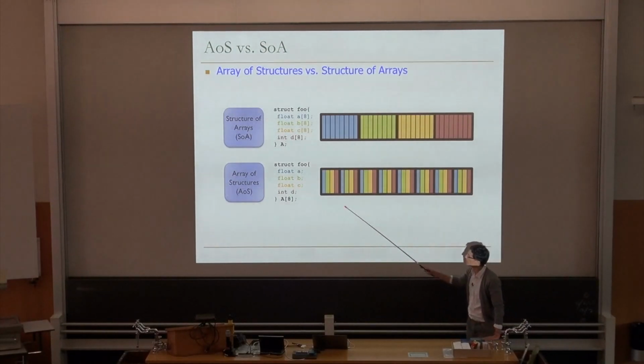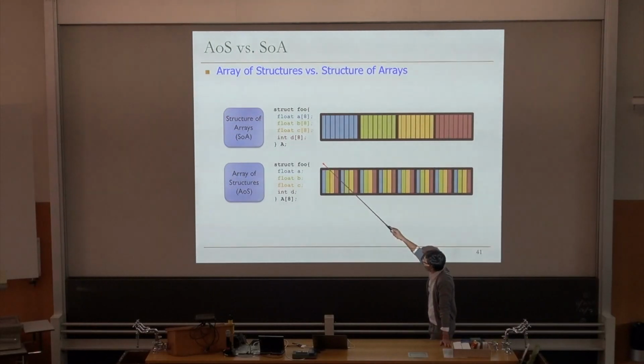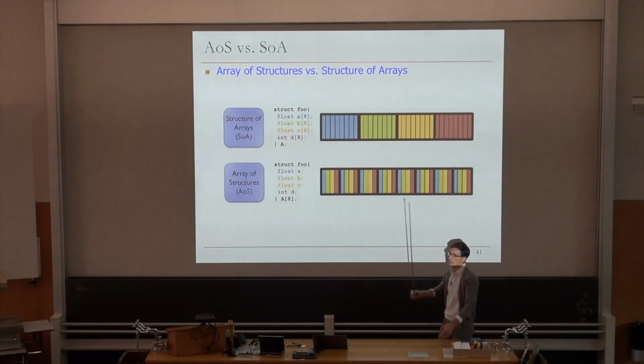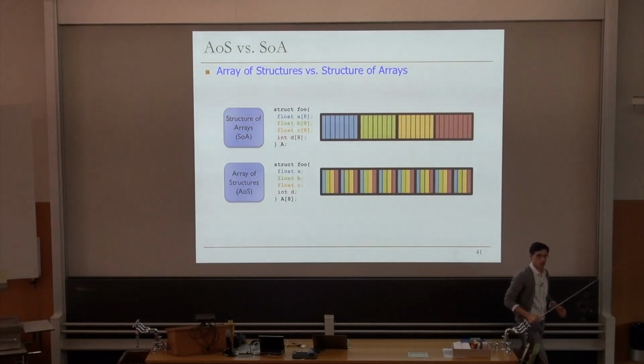However, if we use an organization like this, we will need to have thread 0 here, thread 1 here, thread 2 here, and so on. There will be a stride, a distance between the accesses of the consecutive threads.